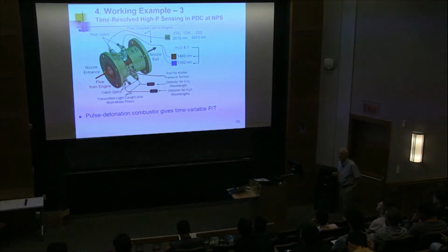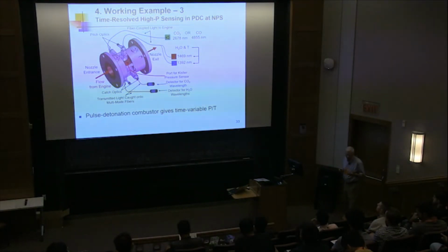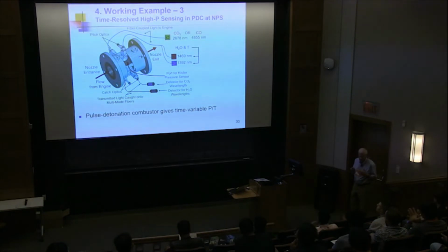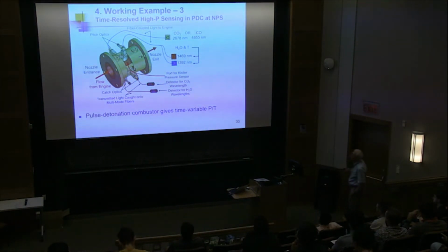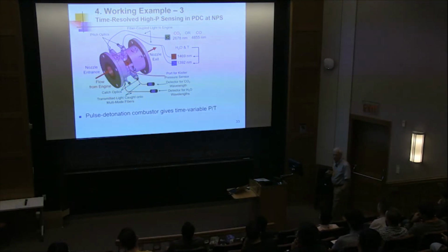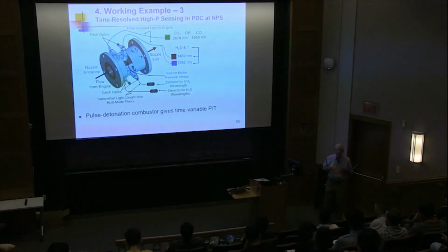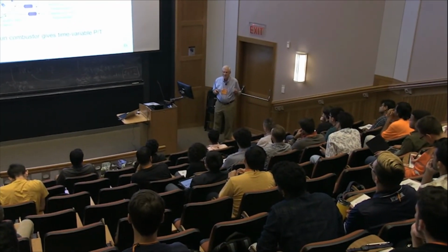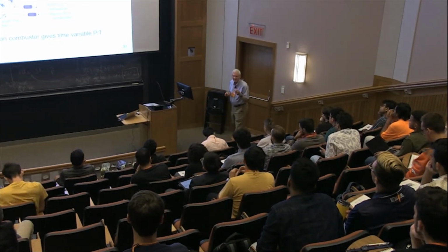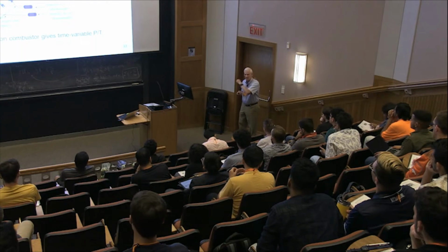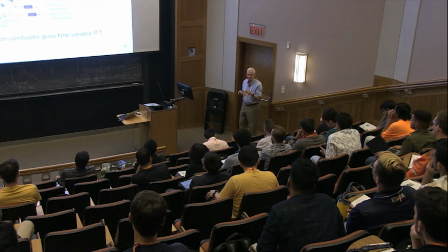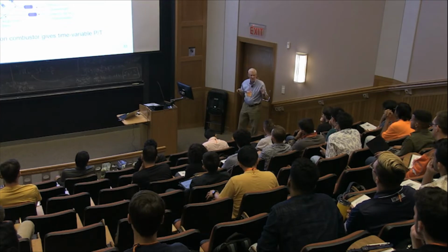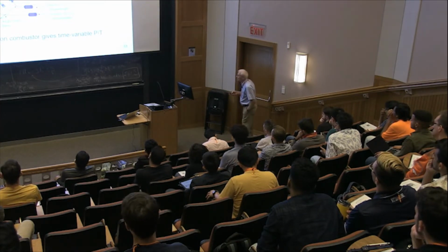What they wanted to know was, is there any possibility you could use this to drive a gas turbine? And what do you need to know? You need to know the enthalpy flux. What's the enthalpy of the gas coming out as a function of time? How do you measure enthalpy? Well, we thought about it and came up with this idea. What do we know about the flow through a converging-diverging nozzle? What do you know about the throat? Sonic. What do you know then? The speed is Mach 1. You know the velocity. And if you tell me the temperature, I can tell the speed of sound, which means I can tell you the velocity. So with that simple idea, you could try to get at what's going on in the system.